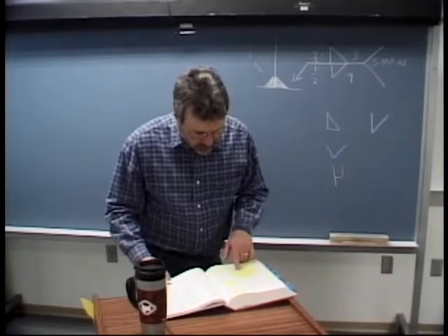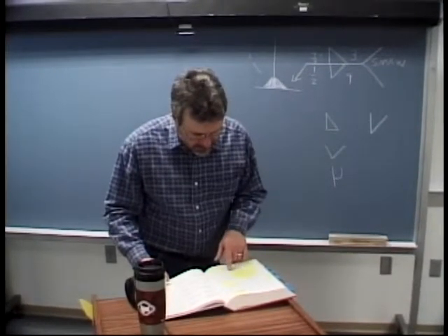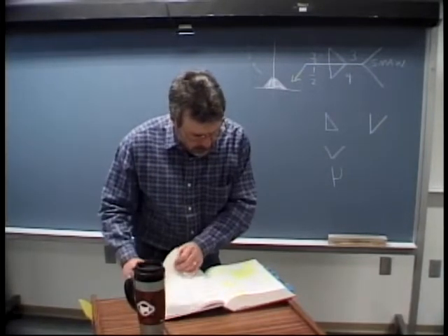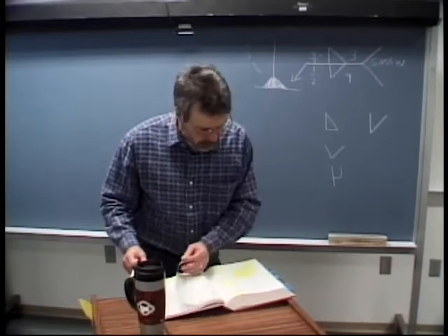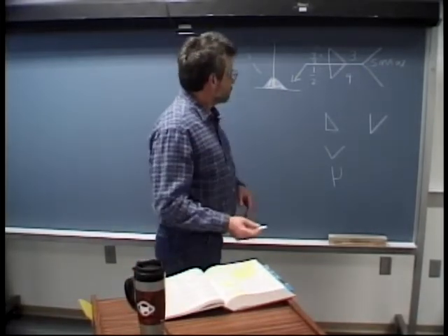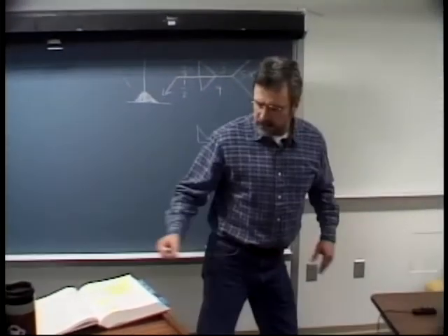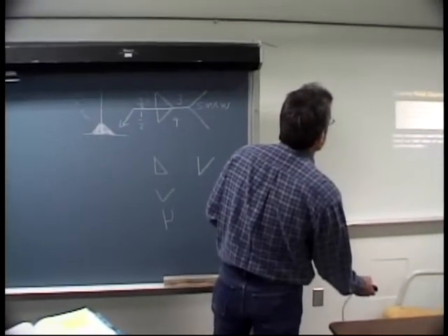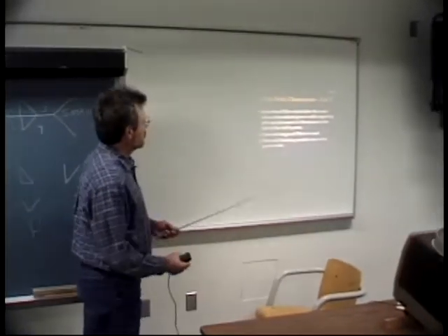Figure 30-7 shows intermittent fillet welds as well as staggered fillet welds. When properly applied, fillet welds do not need to be large in size or necessarily run the full length of a joint. Let me see what slides I have for that here real quick. Don't remember if I had one. Yes, I do. Okay. First of all, let me read it from here.